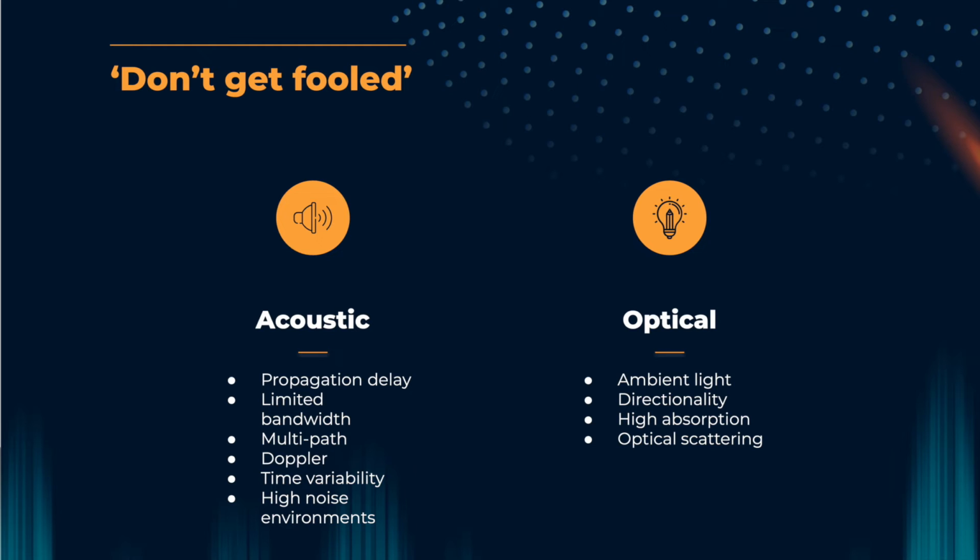Propagation delay may not be a bigger problem, but sound travels very, very much slower than light. So it still takes time from when you transmit to get to the receiver. So do not expect instant feedback. Transmit, receive, and then, that's something you need to play around with to figure out how fast it is transmitting and receiving, right? The third is limited bandwidth. If you are trying to send images and videos, that's not going to happen. It's going to be very, very limited bandwidth, but you can send commands like what we were doing just now.